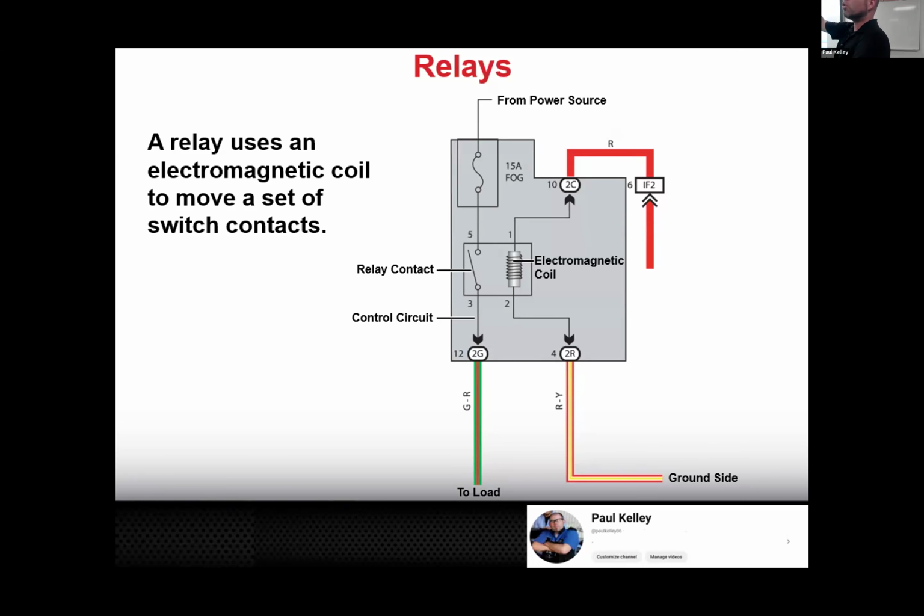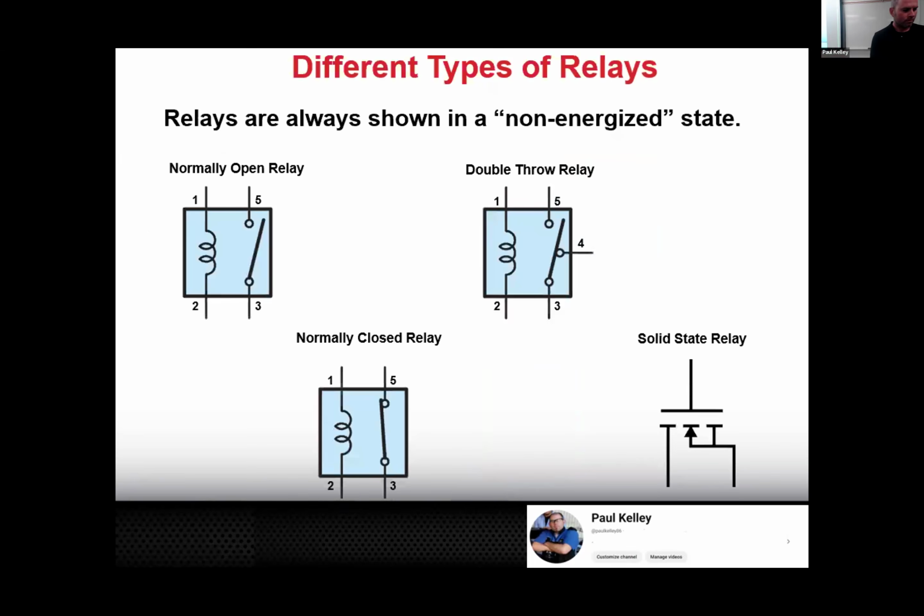So you actually could just pull the relay, and if the fog lights go off, then you put the relay back in and they go on, and on, off and on. And you'd be like, oh, this relay is unable to open. This relay is welded closed. That happens too. I've seen that a few times with cooling fans. Cooling fan relays will weld themselves shut and the cooling fan will just run and run and run and kill the battery. It's for some reason common on some Hondas.